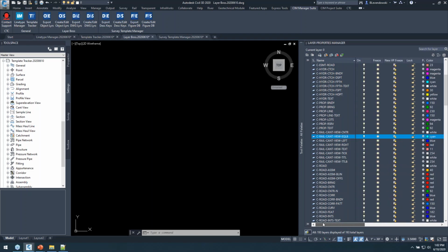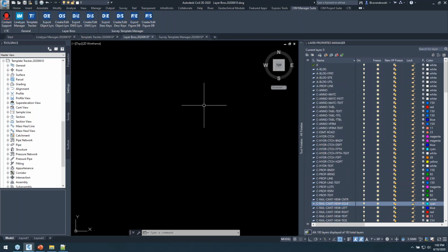And what is this interface basically? It's a big table of rows and columns. What interface is most universal, easy to work with when you're talking about this? It's Excel, right? So Layer Boss, and in fact, the use of it with Layer Manager, is the first of 4 places I'm going to show you where we have tools that allow you to take these clumsy table interfaces, instead work in Excel, do all your changes there, and then sync it back, or write the changes back to your template, right?